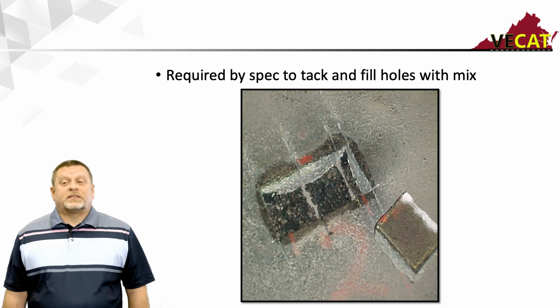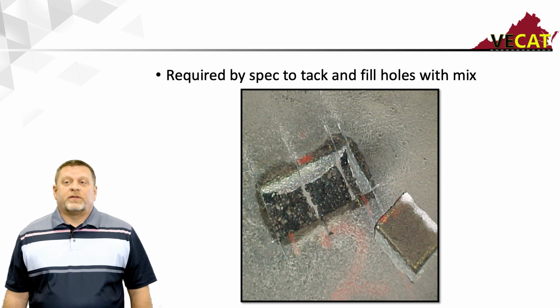Here it is, a nice image of the specimen has been removed, and notice what's left behind is a hole. And by specification, we're required to both tack and fill these holes with mix. It's recommended that you use the same mix that you're paving the pavement with that day.